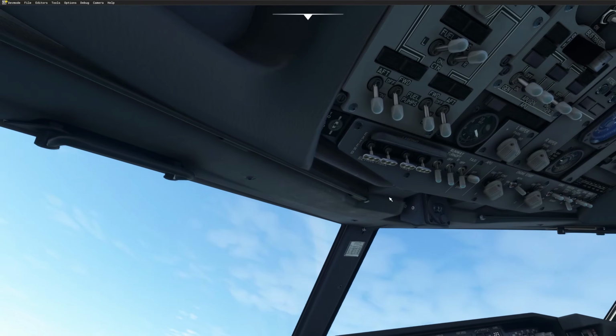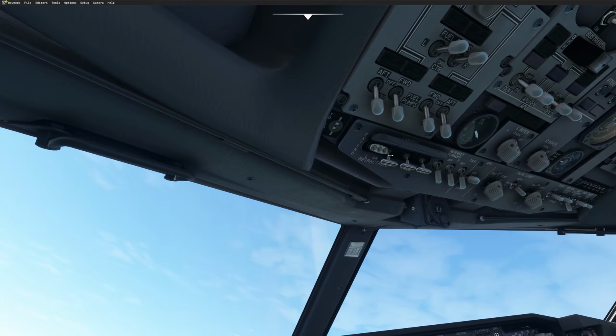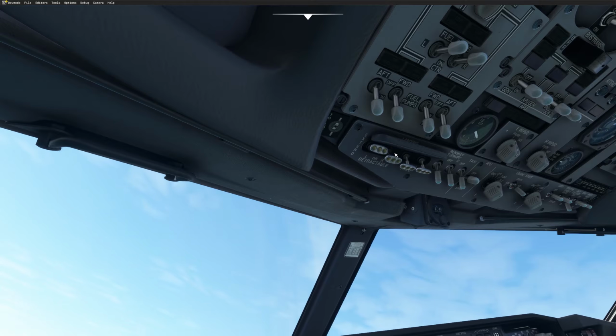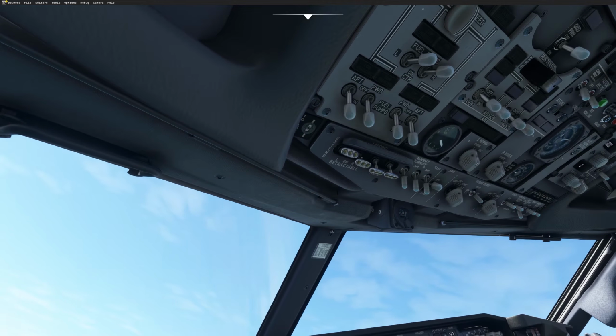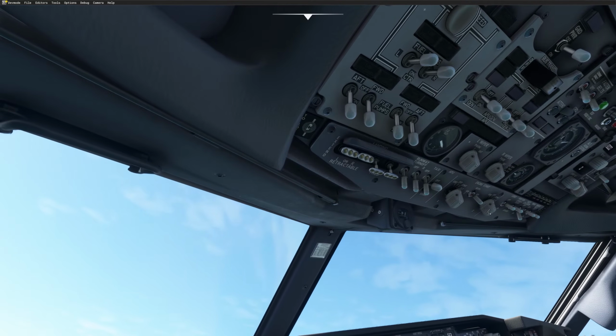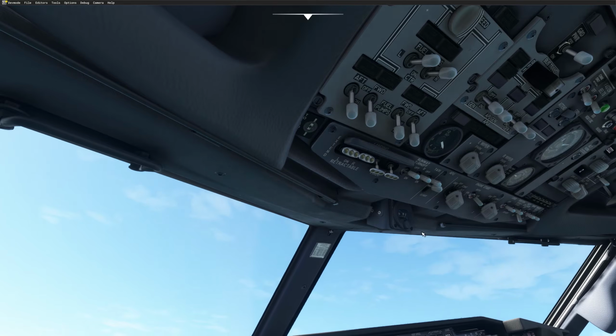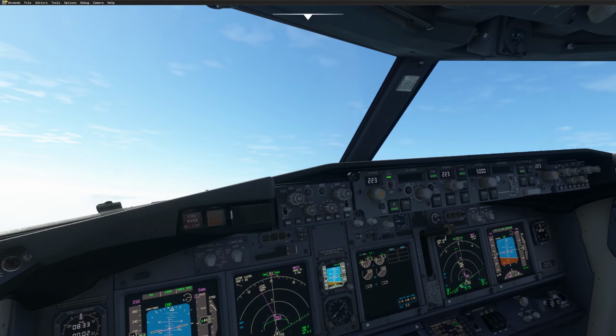After takeoff items, please. So retractable light can go off. Alright, then engine start switch is off, taxi light off, auto brake off, and finally landing gear off.